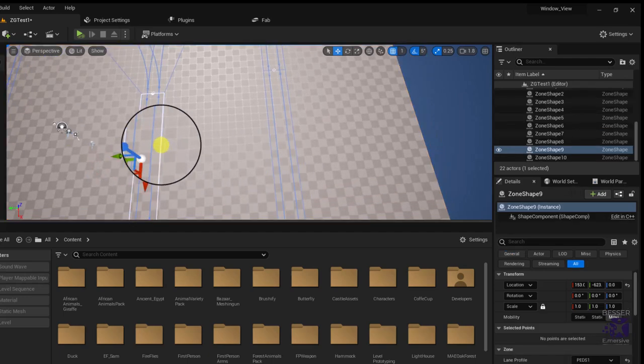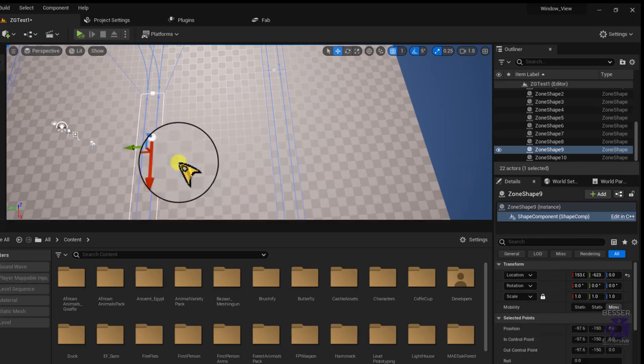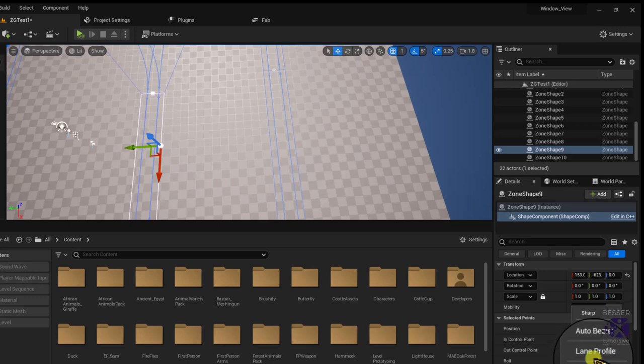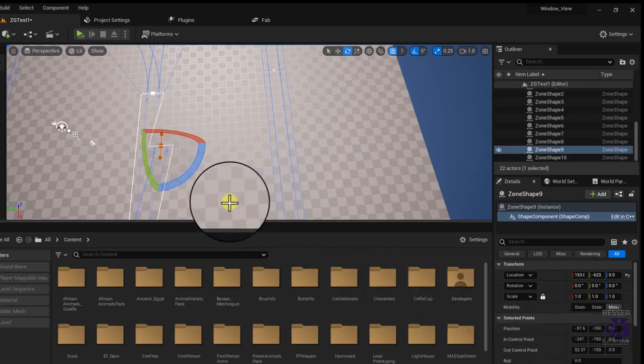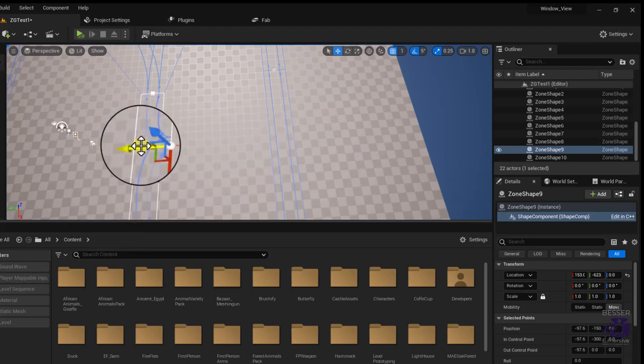Now we will do the same thing to the sides we haven't yet. Select the polygon shape you have in the middle. Add a point near the center that will face the sides we have not yet joined to the middle. Rotate and drag it part of the way towards the side polygon your new point is facing.